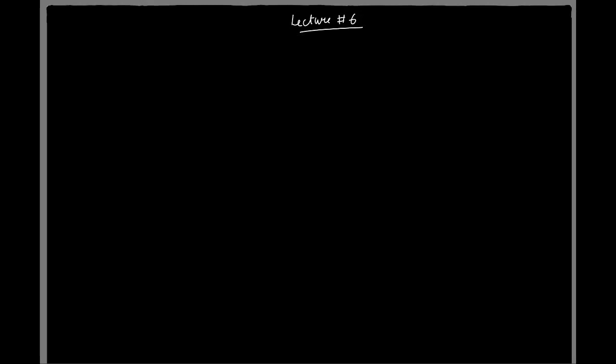So let's start. In the last couple of classes, we have been looking at the telescopic cascode, and the idea was to have a PMOS cascode. Let me draw it quickly once. So here we have the PMOS current source, and then we added a PMOS cascode. We also had an NMOS cascode, and then the NMOS diff pair.